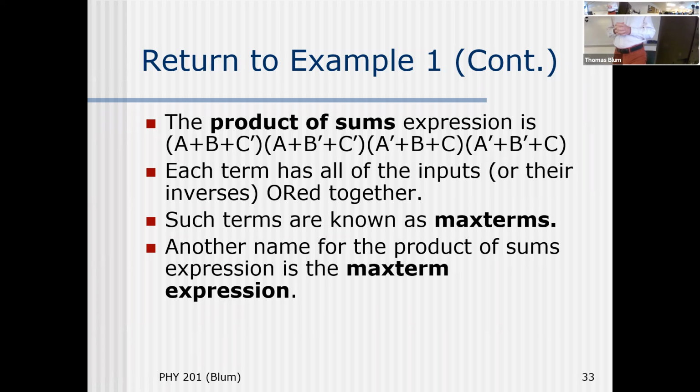And so when I write the expression, I need parentheses, because just like you do multiplication before you do addition, unless you have parentheses, the same thing is true for ANDing and ORing. So that's another reason I like this notation, it seems natural to us. We're used to that order of operations, that idea of precedence in our regular algebra, and it comes over to our Boolean algebra. So if I wanted to perform some additions and then multiply them, I would need parentheses. And that's the same thing if I want to do some ORing and then do some ANDing, I need parentheses.